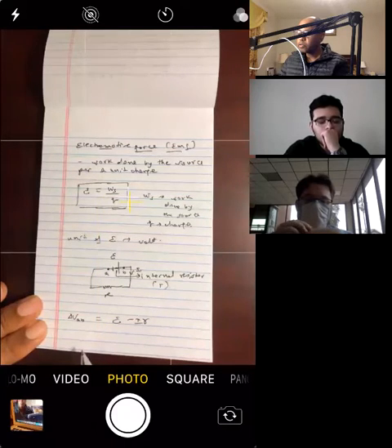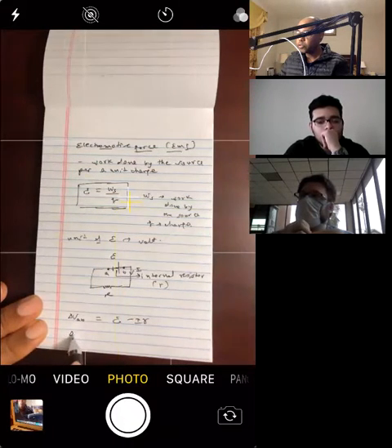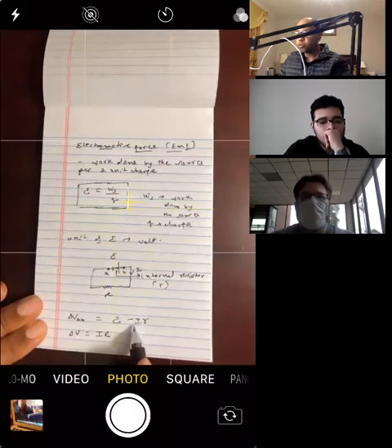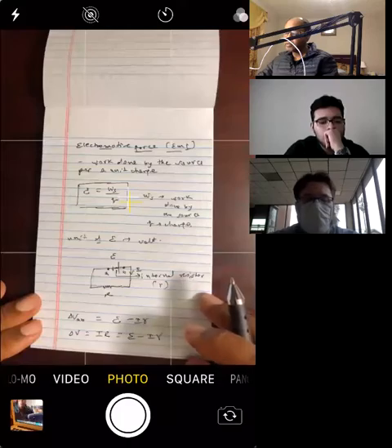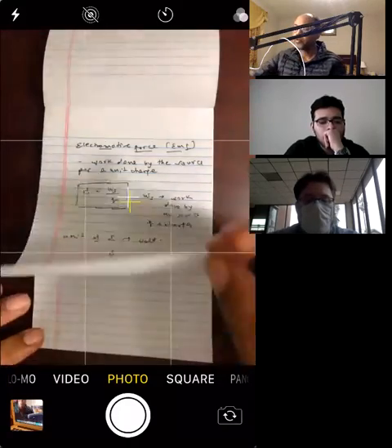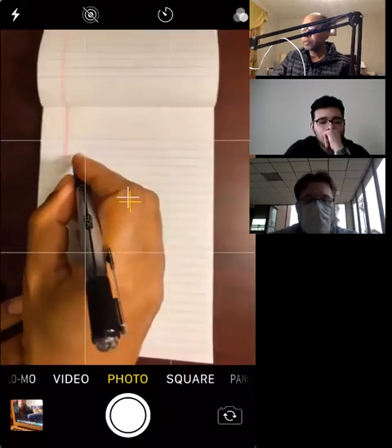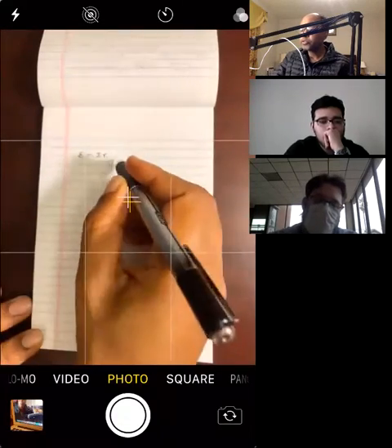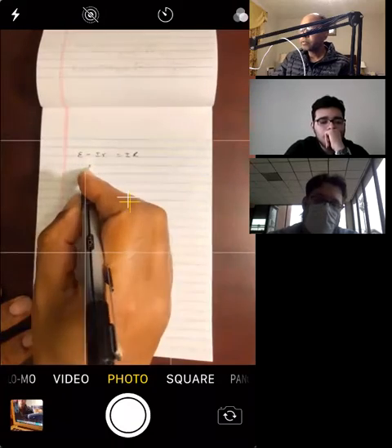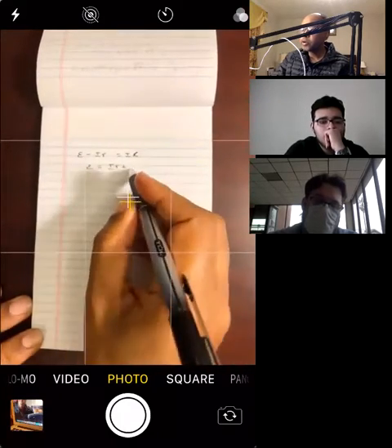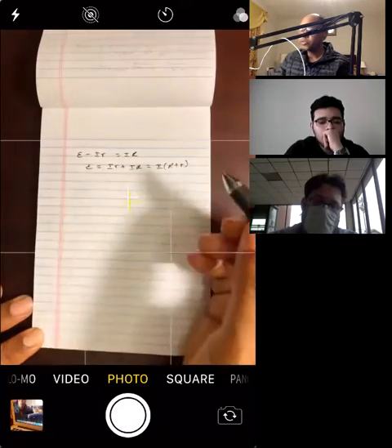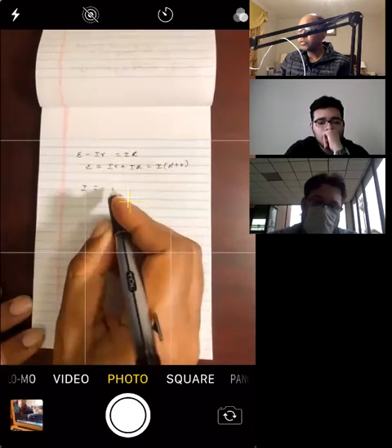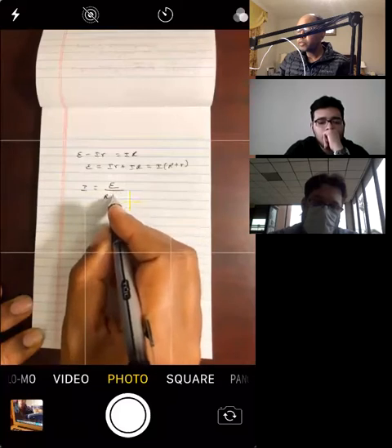So you can say the potential difference across this resistor, current times resistance, is also equal to this one, E minus Ir. We can use this formula to calculate the current in the circuit. EMF minus the potential drop in internal resistance equals I times R. Taking the other side, you've got I small r plus I capital R, which is current times the external resistance plus internal resistance. So you get the following formula for the current: the current is EMF divided by the external resistance plus the internal resistance.